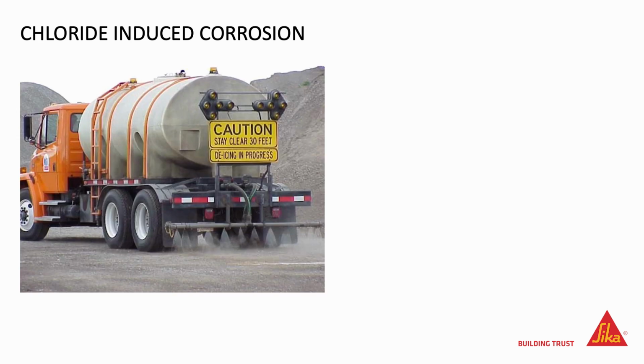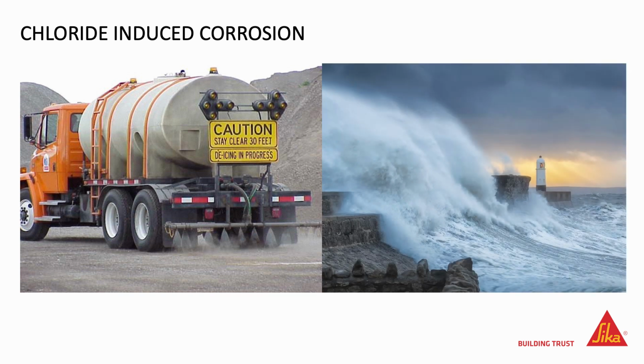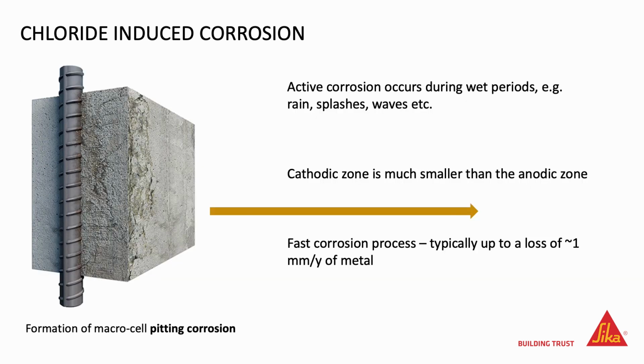Another root cause of corrosion in reinforced concrete is the penetration of chlorides in the concrete, reaching the reinforcing bar level. These chlorides can come, for example, from de-icing salts used in winter, or from salt water, amongst other sources. When chloride ions reach the rebar, a localized large anode is formed with the formation of hydrochloric acid that also lowers down the pH of the concrete to a very low level. This large anode is responsible for a typical corrosion due to chlorides, which is pitting corrosion.